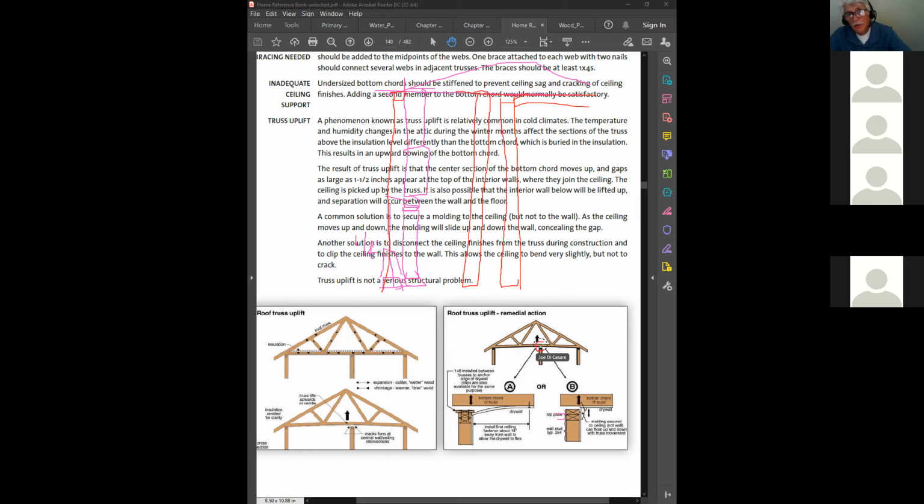So what you have to do then is go outside, remove the last brick, and put the structure back onto the wood. And it's end of story. So that's another problem that occurs. And people ask themselves, well, what do we do? Just tell the mason to come back, and he should never have put his last brick there. You always have to make sure that you have at least a 3/4 inch space between the last brick and where the wood truss is going to be sitting on top of the bricks. You understand?